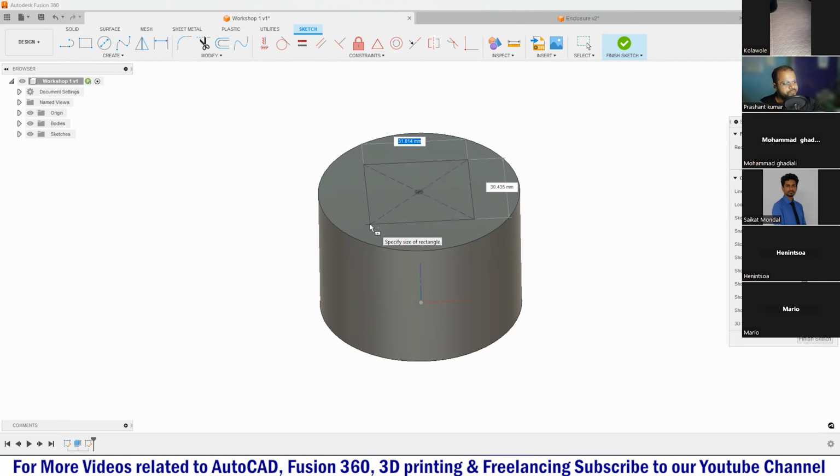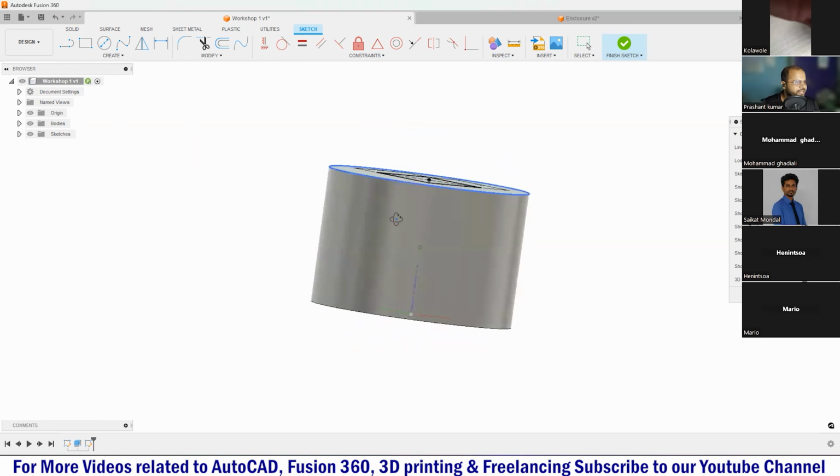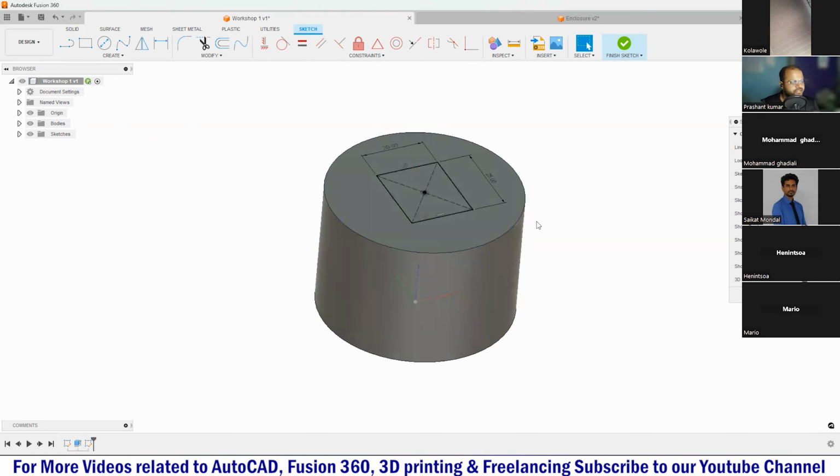Now I just need to specify the dimensions of this rectangle, I mean the length and the width of this rectangle. So I can just write 20 and press Tab to move on to the other box, right? Again, we'll write 20 or maybe 25, something like that. And the moment I press Enter, here you can see I have created a rectangle like this on the top of this cylinder, right?